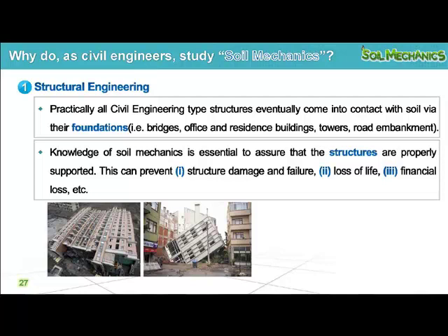So soil mechanics is very important. Even if we build our building with high quality, as you can see in this picture, the body of the structure seems very good, still in the same condition, not broken, but because the foundation is not good or does not have enough bearing capacity, it can make this building collapse.